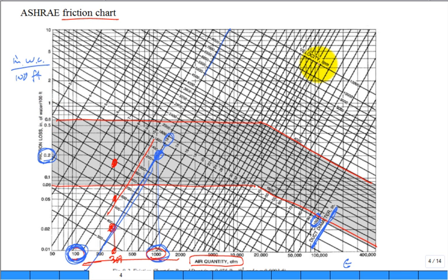They also show you the feet per minute, right? Here is 700 foot per minute, 1,000 foot per minute. You don't want over 1,000 foot per minute in your home. So a lot of times the home is kind of zoned right in here. There's your home calculations. You don't want it to go faster. Commercial calculations would be outside of that zone.